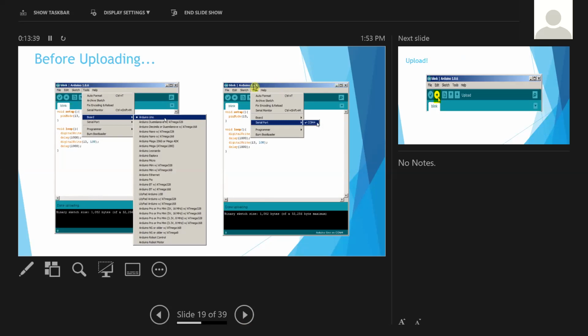So go down to Tools, Serial Port, over to the right, and make sure that you have a check mark to the left of the COM that you've set your USB up to. Because if you have your cell phone connected to your computer at the same time and it's charging, it might be connecting to your cell phone and not the Arduino. So you want to check those two things before uploading.